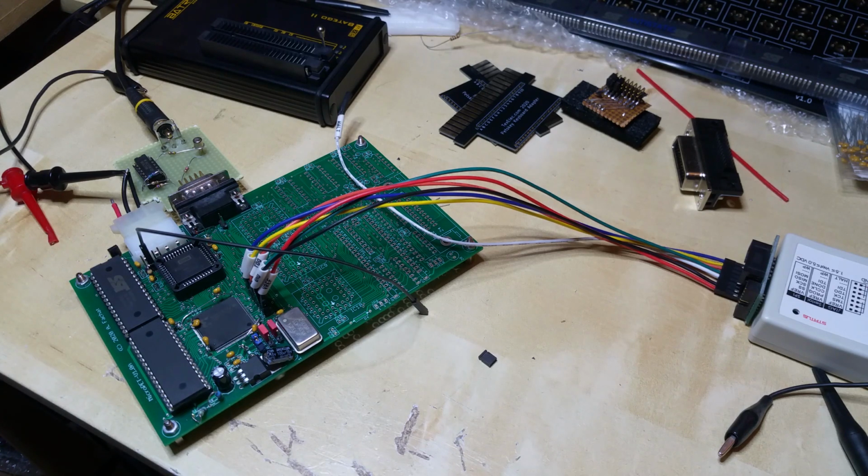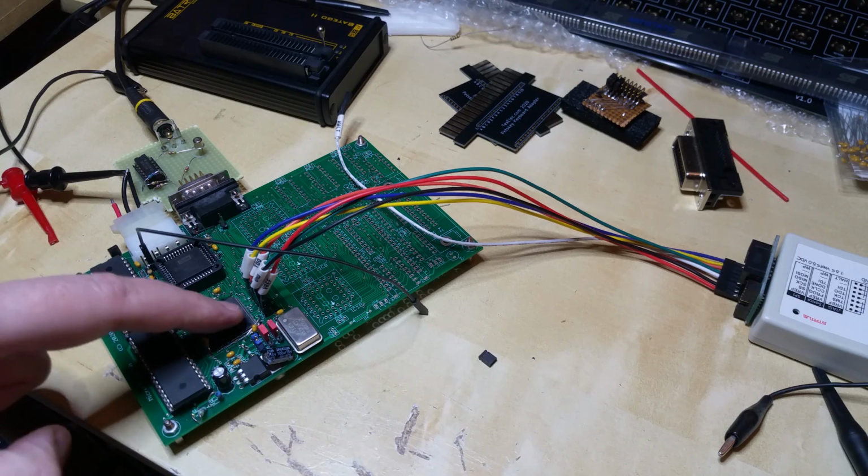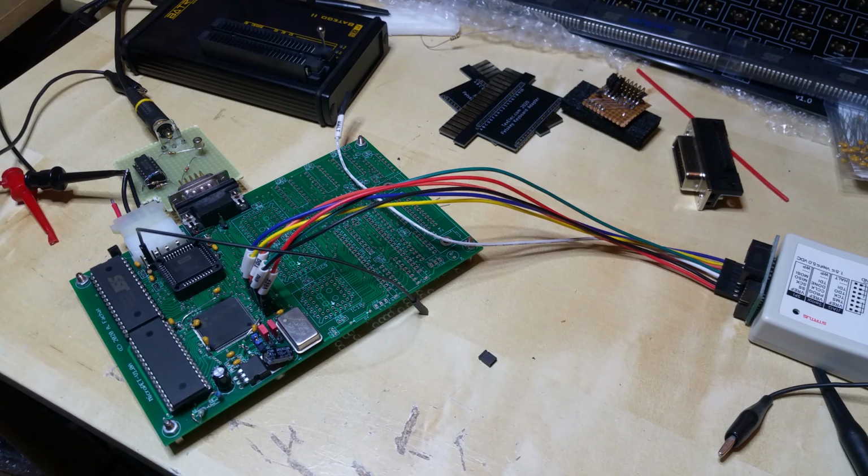And I have been programming the ROM with a NOP sled, so basically 4 kilobytes of area just filled with the CPU's no operation instruction, and have been restricting the CPU, using the mapper in the CPLD, to just that single 4K block of memory. So what the CPU should do is just read those NOPs and then just continue cycling the program counter. And that's what we can see next on the oscilloscope.